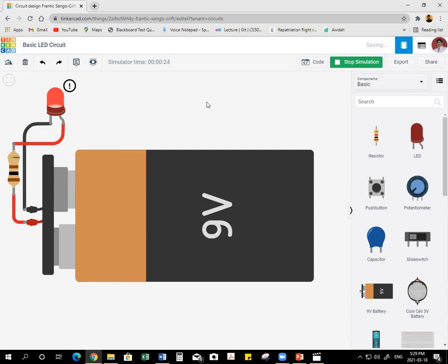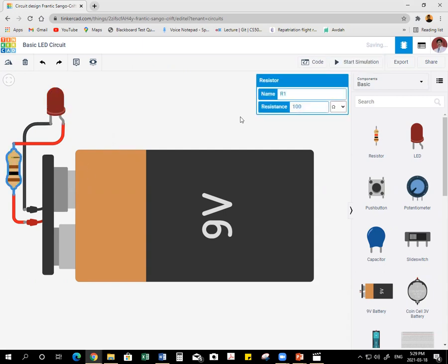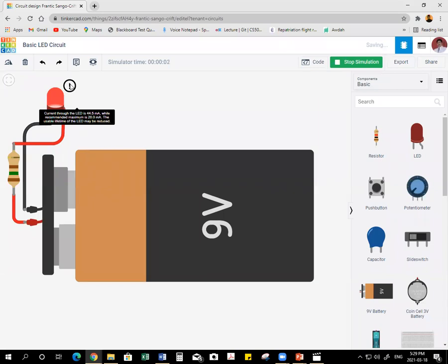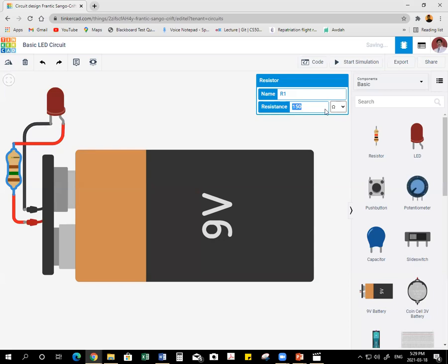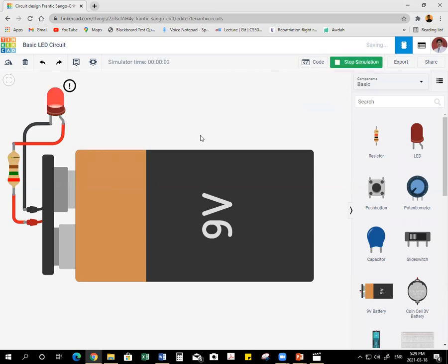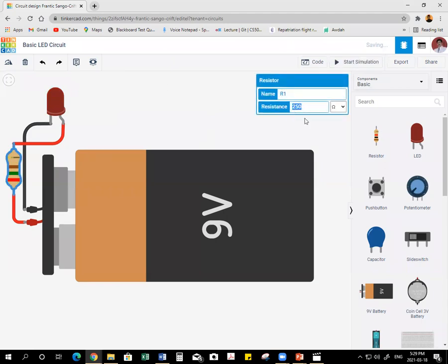Another 50 ohms, if I add, I think it is better. We have 150, and let us see what's happening. Now start simulation. Still 45. So we can have 220 ohms, let us take 250. This is the fashion in which we proceed with our simulation. Again, see, we limited the current from 44 milliamps to 27, 50% we limited. Another, we just double the resistance value, maybe it will be safe now.